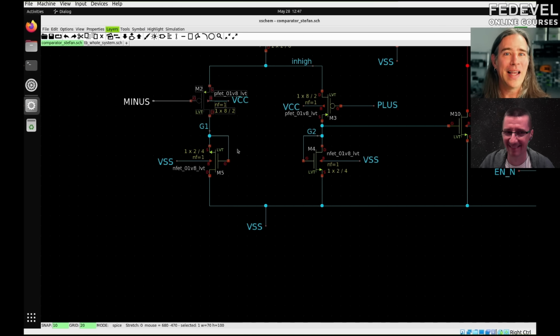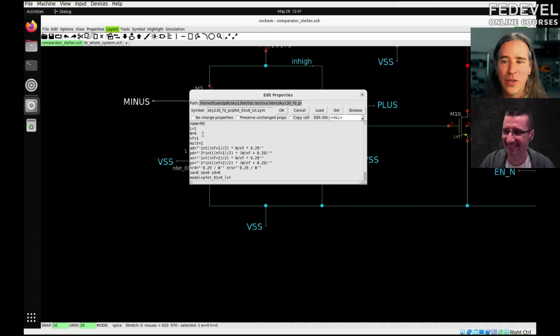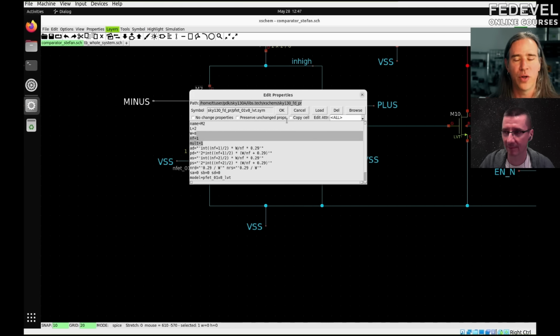But the thing is, when you're actually in the chip, at least for this technology, they're perfectly symmetric. So it doesn't really matter as long as you connect them the right way. So I didn't even do it right. But anyways, you have these things, but you also have number of fingers and multiplicity. Multiplicity is just like having many in parallel. You want these characteristics, but you want more current to go through, just add more in parallel, and it does some work for you. Good.